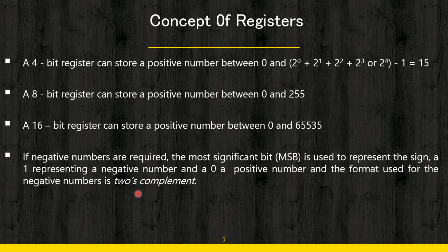I am not going to talk on that because you have already covered all these topics at your graduation level. But these are the basic concepts. Your register can hold positive data as well as negative data, and you know what the range is right now. Now, if I ask how much an 8-bit register used for storing positive as well as negative data, a signed data rather, will hold: you can see this is 0 to 255, this 255 will be divided by 2, so that much in the plus and that much in the minus.